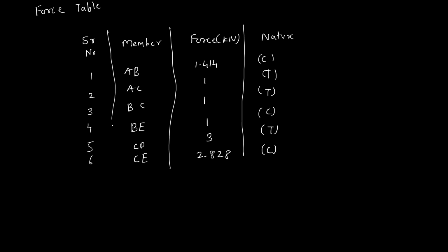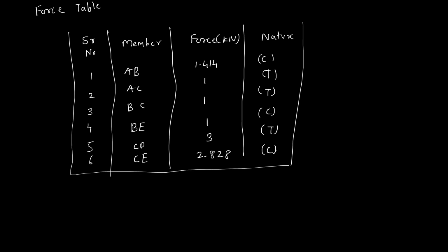So you have to summarize your analysis by using such a force table. Looking at this table, you can directly say which member is in compression and which member is in tension, and what is the value of force in each member. Okay.